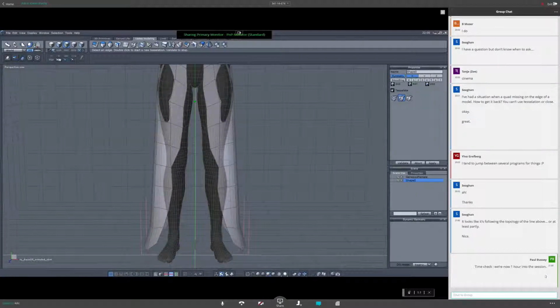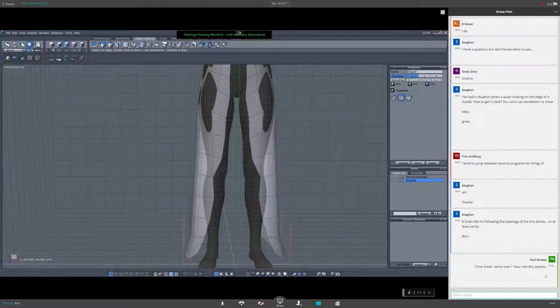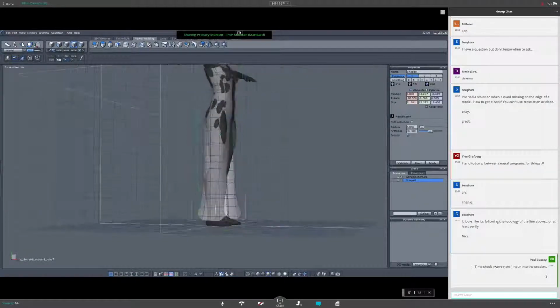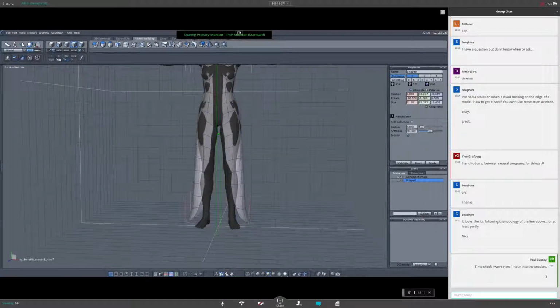And then I also did something else I can show you here. I welded a few points. You do this by selecting the two you want to merge, and then press weld points. This is how I did this. Okay, going back. This makes for this nice zigzag shape here.